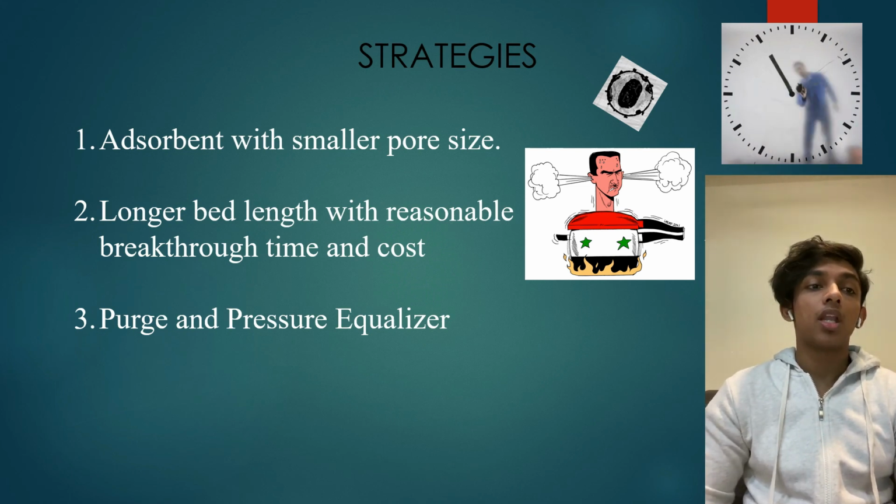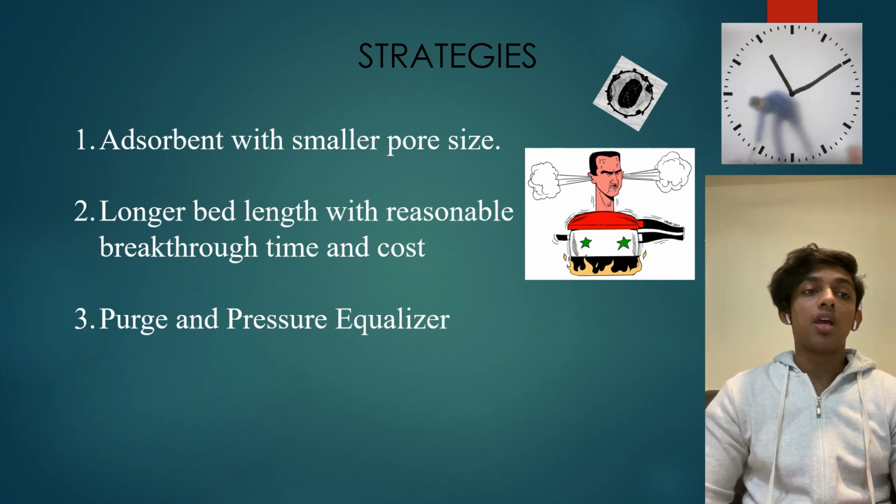Purge and pressure equalizer. The proposed PSA sequence increases the hydrogen recovery by introducing a purge step, which uses a recycle of CO2-rich stream, and a pressure equalizing step.